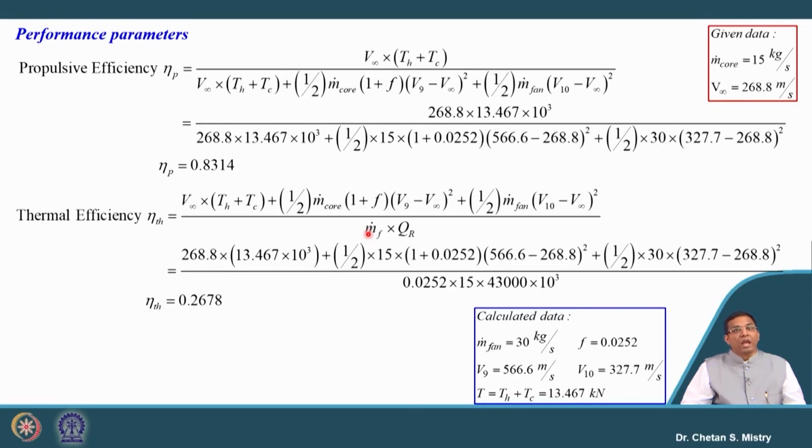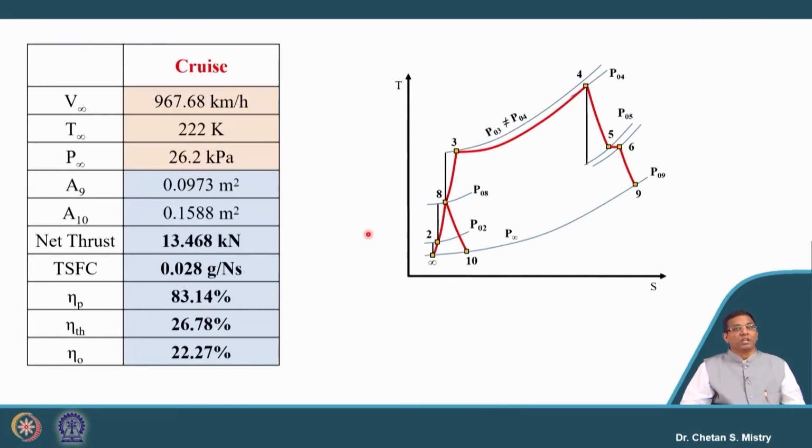Okay. And we have our overall efficiency, the thermopropulsive efficiency, which is nothing but propulsive efficiency into thermal efficiency. This efficiency comes to be 22.27%.